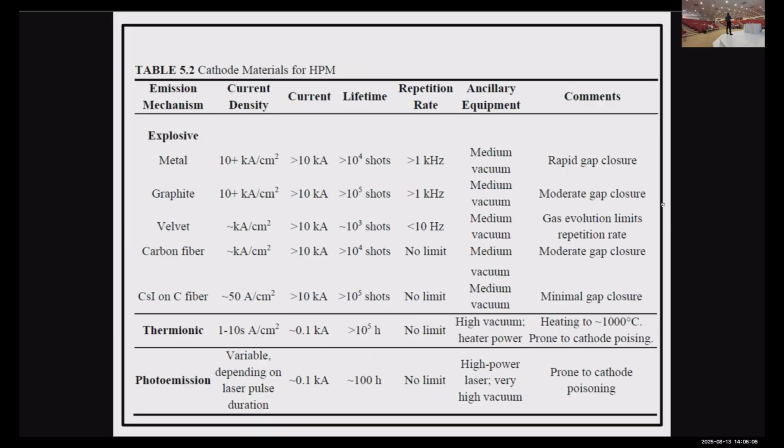But what you see here is basically the part we call explosive electron emission. Explosive electron emission is nothing but field emission, except that we are providing too much electric field intensity, 100 kilovolts per centimeter or above, up to 1 megavolt per centimeter. These high fields will cause the material that you use for your cathode to suffer from what we call explosion of these small micro points.